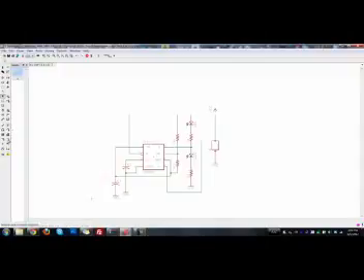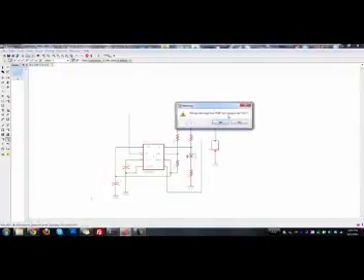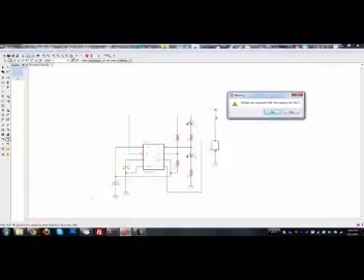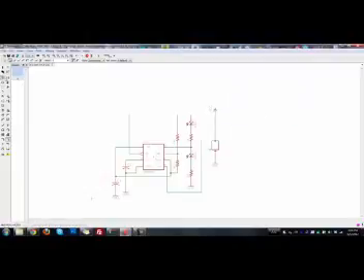Okay, so this can get wired right up to here. Again, it's asking if we want to merge this line, which was called $8, so just a variable 8, into the VCC net. So we'll hit yes. And this line does not need to be that long. So click on this, just drag it down, just like that. And now our battery is kind of this self-contained thing over here. And we can do the same thing with everything else.